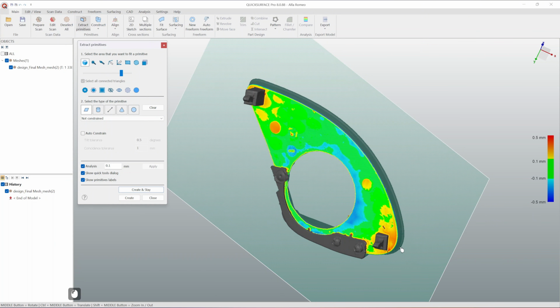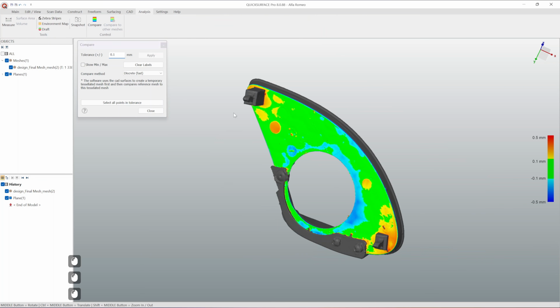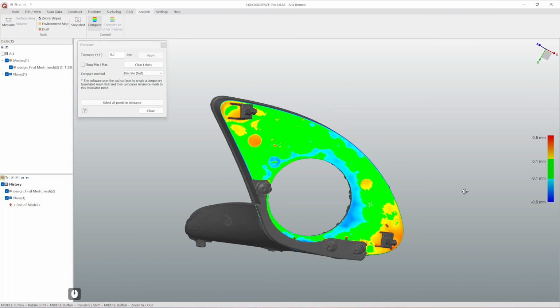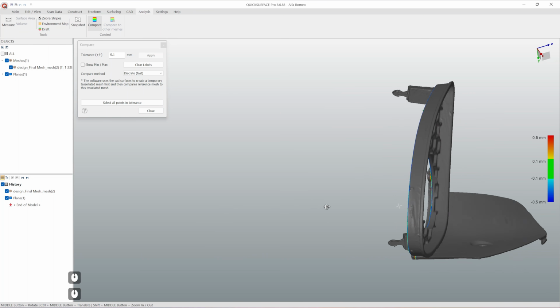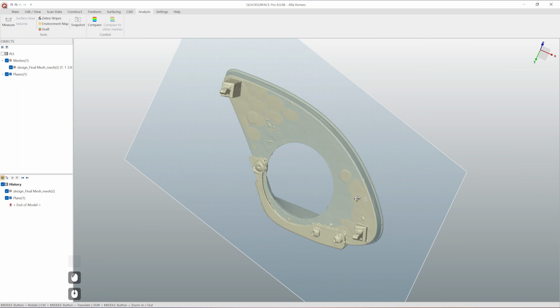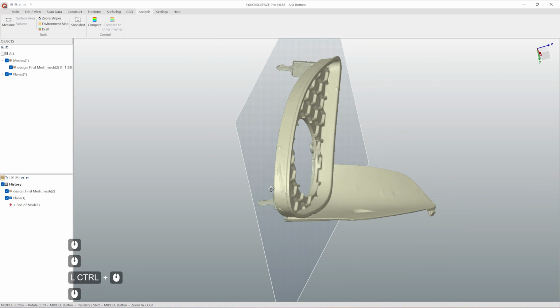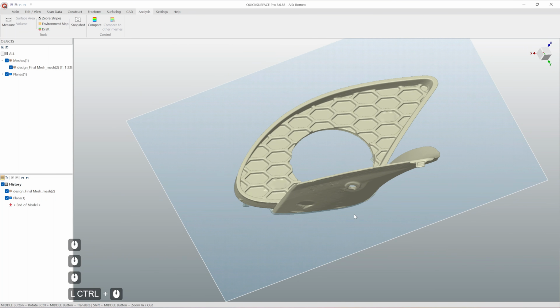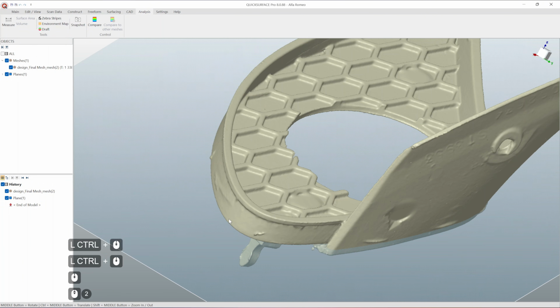So actually here we can see that it has some really slight curvature here, but it's like 0.something millimeters. So most likely this is just a deformation because this is a used part and has been installed in a bumper, living in the sun and so on. So in this case, like 99.5% this was designed as a flat, and that's why I'm going to actually also design this as a flat surface here.